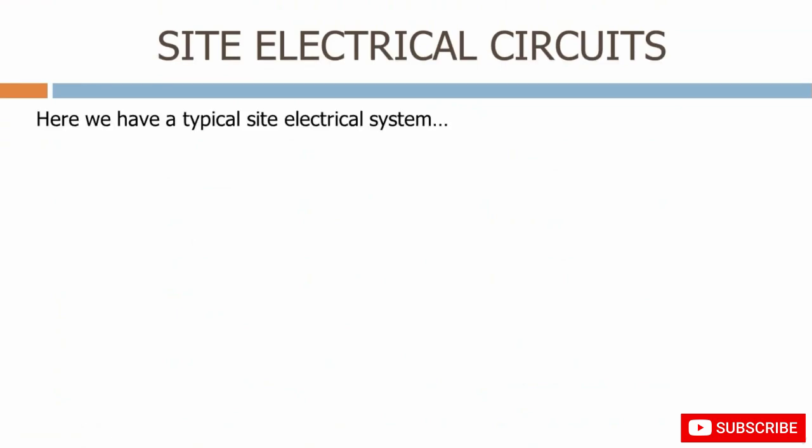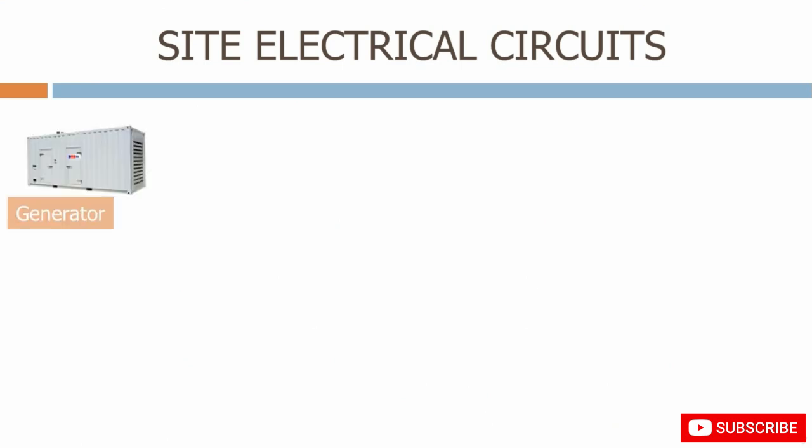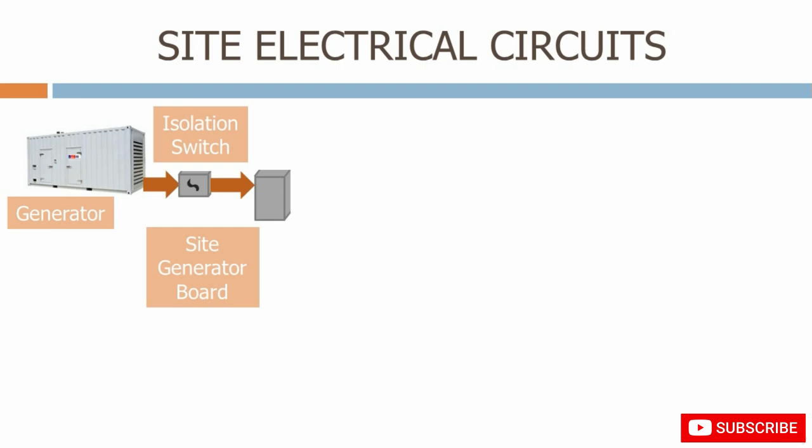Here we have a typical site electrical system. Firstly, we have the containerized generator. This is normally a three-phase device operating at 415 volts. We connect the generator to a site isolation switch. This has the ability to disconnect the whole site electrical system in case of maintenance requirements or an emergency. We then have the site generator board, which feeds power out into the network.